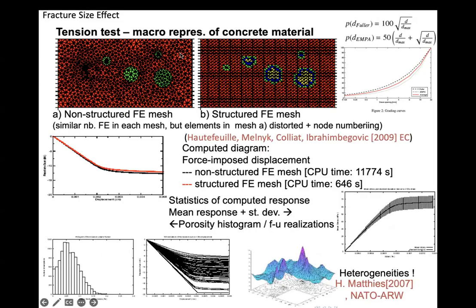So this is your specimen done in 2D. The green things are aggregates. It's done in terms of, let's say, the aggregate curve, either full or empirical, you know how many big and how many small we put, only you don't know where they're going to end up. So we do this as a Poisson process, rather not to overlap. It becomes a Gibbs process, and you fill in the domain with the corresponding aggregates,